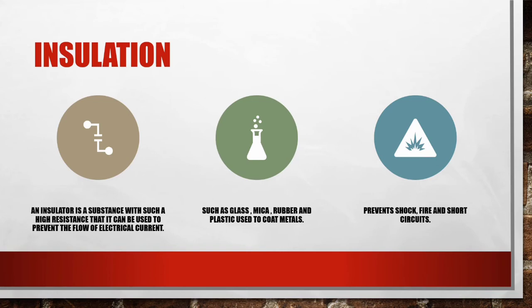Therefore, all electrical cords should have sufficient insulation to prevent direct contact with wires and should be checked prior to each use. Before each use, portable cord and plug connected equipment should be visually inspected for external defects such as loose parts or deformed and missing pins.